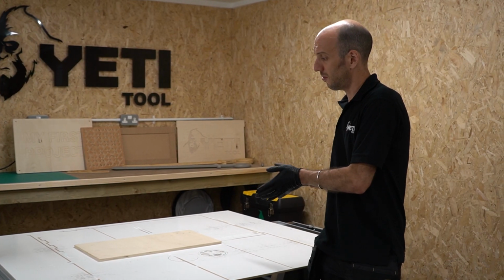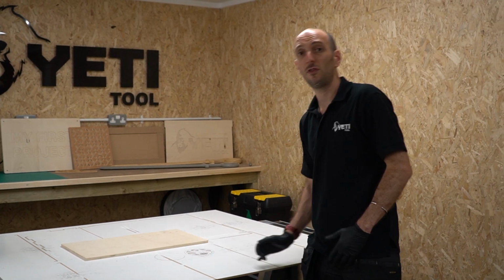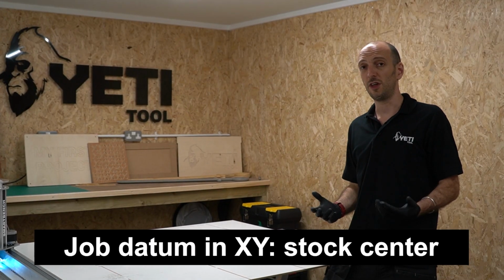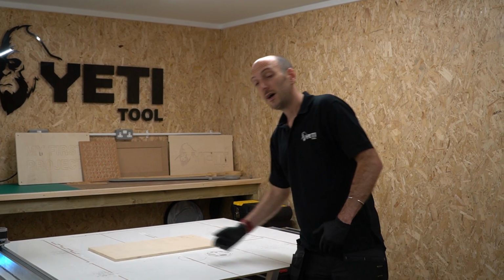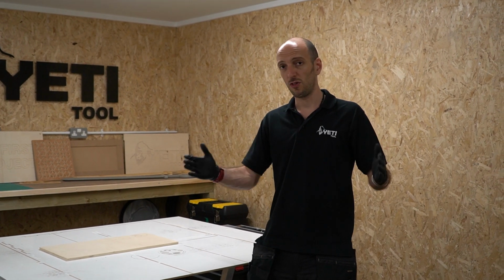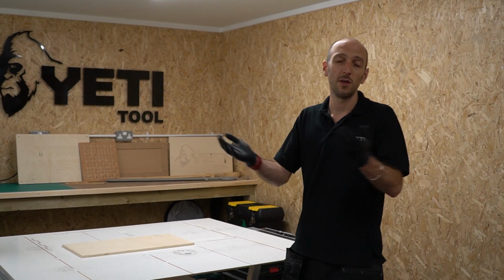One downside with it though is if you're into precision work, you need to make sure that this corner is sharp so that it gives you a nice reference point to datum from. Alternatively, you could put the job file datum in the center of the stock, and that can be useful if you're cutting a sign where you want that detail to be symmetrical to the stock that you have available. Similarly, it can also be useful if you don't actually have a corner to reference on. It just depends on the stock that you're cutting from.